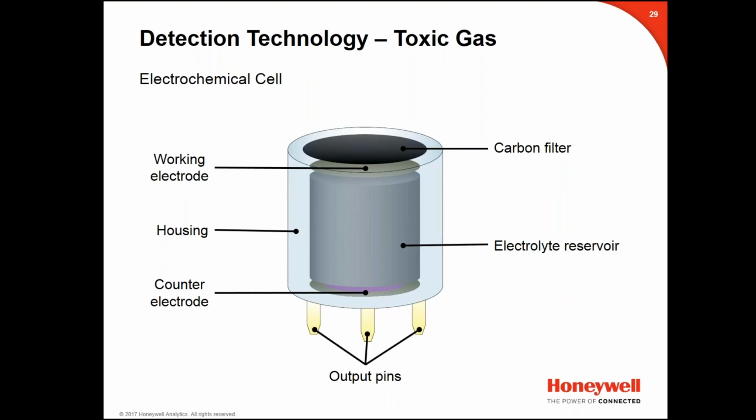Similarly, if you use this in a very low humidity environment, because it is a hydrophobic membrane, the moisture from the electrolyte reservoir will be pulled out into that drier humidity environment. Now, if enough of that moisture gets pulled out, we end up with a very acidic electrolyte, and that's going to, over time, consume the counter electrode and the working electrode.